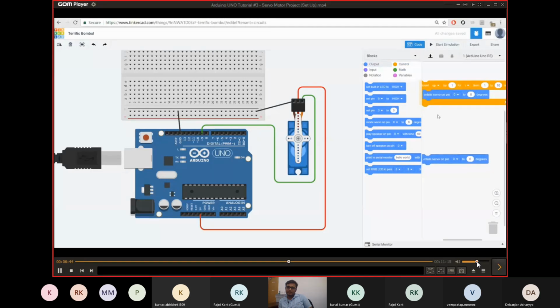So what do we have? We have count up. We're going to start at 1, and we're going to move from 1 to 179. Even though this can probably go to 180, I'm a little concerned that that 180 value might reset it and cause it to spin. So I'm going to have it count up from 1 for position. Position right now doesn't have a value.